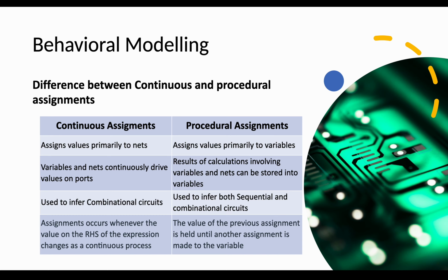Procedural assignments assign values primarily to variables. Results of calculations involving variables and nets can be stored into variables. They are used to infer both sequential and combinational circuits. The value of the previous assignment is held until another assignment is made to the variable.